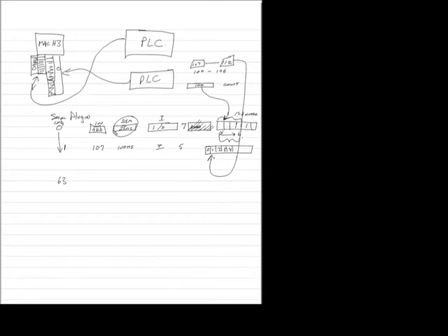So if you're programming a brain, you know which configuration is specifying the data coming in, and you know to grab it in the first 5 memory locations since you're only transferring 5 registers. These don't have to be contiguous areas. Each configuration could just look at one register, for example. So you may want to transfer address 100 in at 25 milliseconds, but maybe address 101 you want to transfer in every 100 milliseconds because it's not as important. Using this method of timing and selecting which registers are going in allows you to set a priority for the data which is coming in.